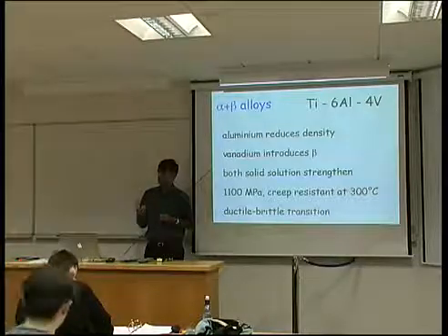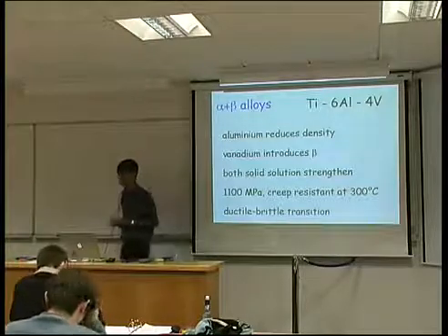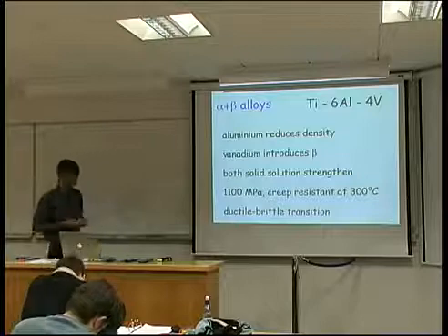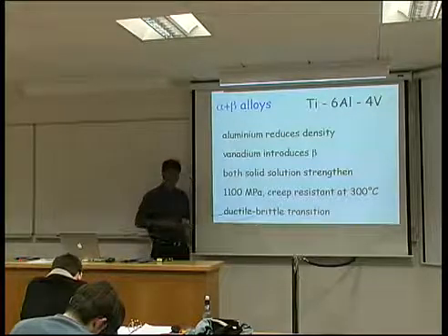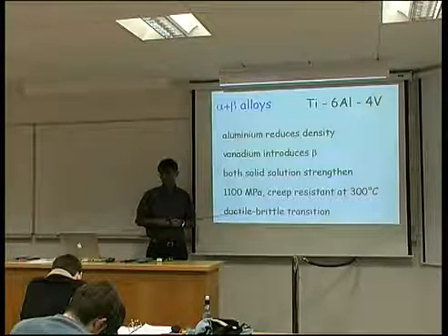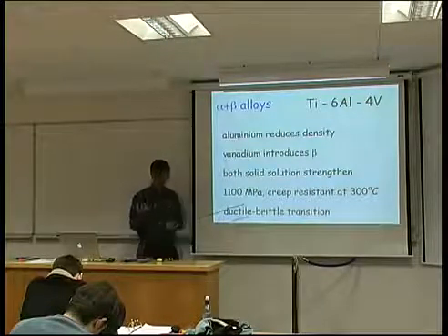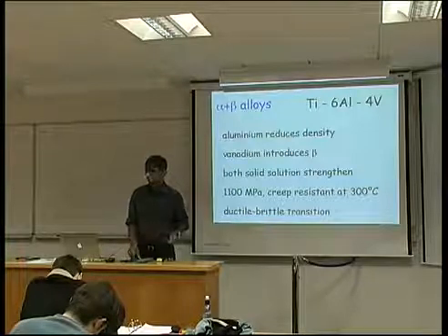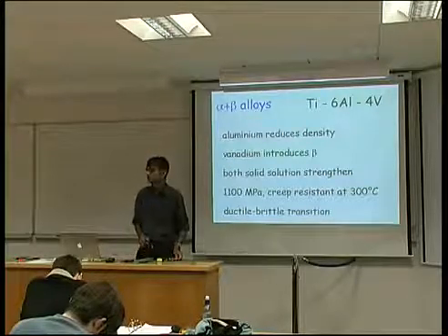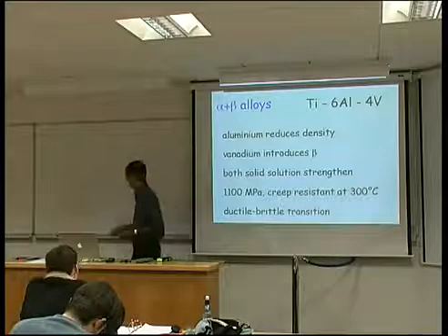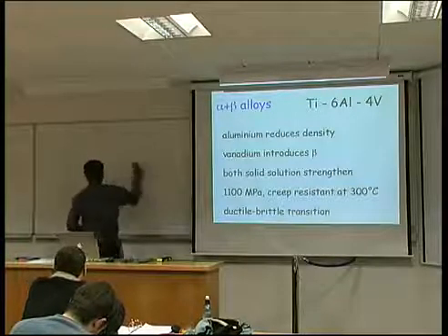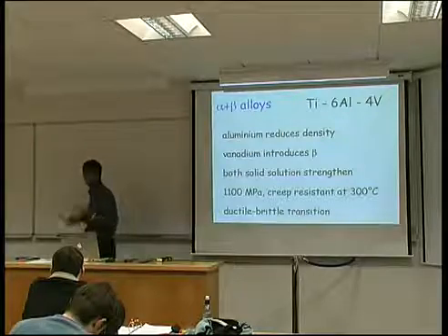So this is the alloy that we will come across most frequently when we are discussing titanium. Now, of course, the body-centered cubic phase, that is the beta phase, has a ductile brittle transition. Okay? Have you come across a ductile brittle transition before? Yeah. So let me just quickly explain to you why you get a ductile brittle transition in body-centered cubic